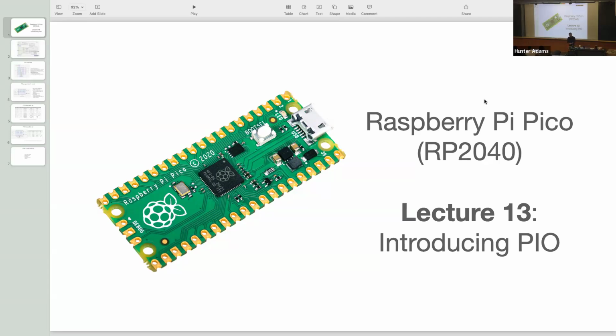Now, if you're okay with a slightly less rich color palette in your Galton board, maybe you're okay with a Galton board that's just black and white, you could reduce that to 1-bit color. And then in the same byte, instead of holding color information for 2 pixels, you can hold color information for 8 pixels. Which radically drops the amount of memory that you're using for VGA color information and frees up more memory for more balls in your Galton board. So in the event that you find that you're memory constrained, an understanding of how to modify this is going to be really important so that you can drop the memory consumption of the VGA driver. Sacrificing color resolution in the process, but kind of who cares, right? There's no requirement with regard to color for this lab.